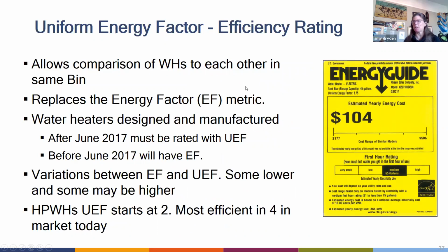So first, I just want to talk about efficiency. We have the uniform energy factor. It's a slightly altered energy factor, which we may be used to for heat pump water heaters, or for water heaters. This changed in June of 2017, and essentially it bins water heaters in the same kind of category. So it's more of an apples to apples comparison versus the energy factor. We can't always say an EF is going to be lower or higher than a UEF. They vary depending on the tank size and things of that nature.